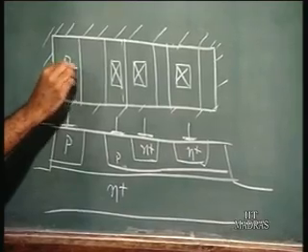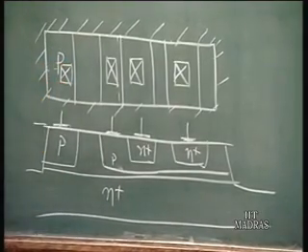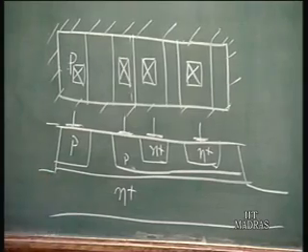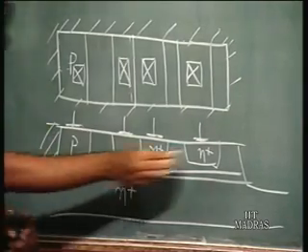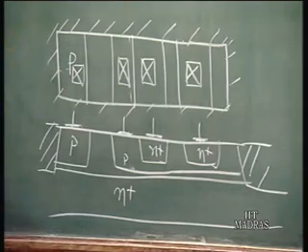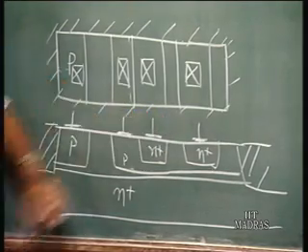You have one more contact here, that is the injector contact. So this is the I squared L structure. This is the oxide regions, isolating. It goes all around. So this is the base, these are the two collectors.